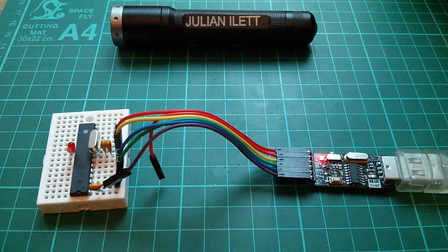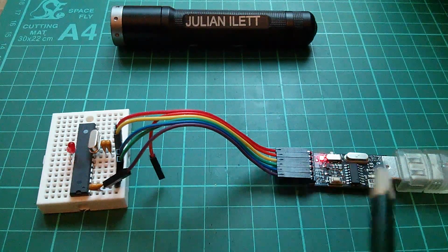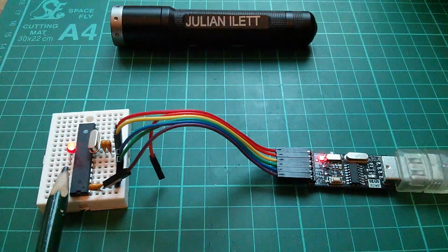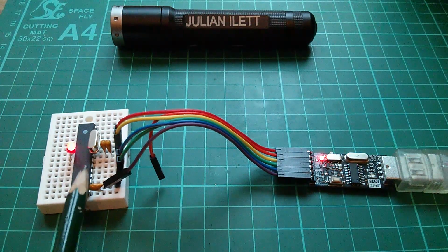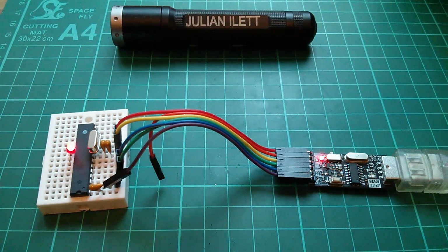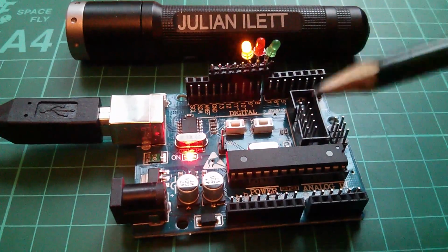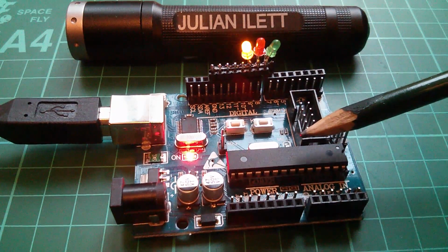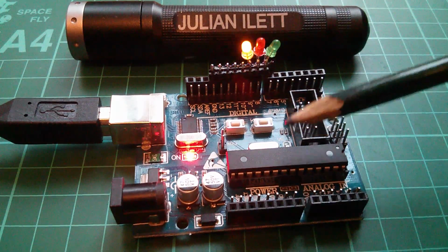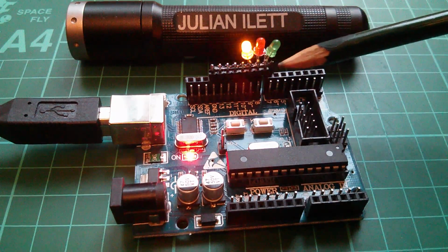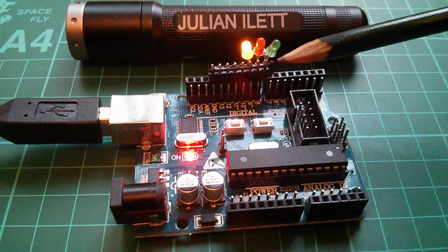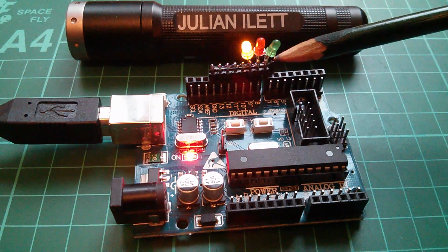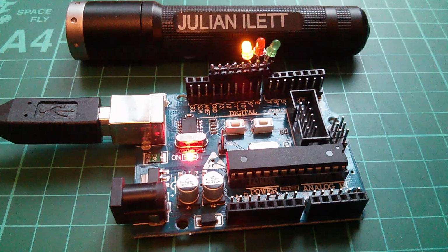And yeah, that seems to have worked. The bootloader has taken, the program has gone in, it's the fast blink that I had earlier. This chip is working as an Uno. So that's it. That's how to use an Arduino as an ISP, an in-system programmer. And I do think that it helps to build this little 3 LED array, because then you get to see the heartbeat, any errors that might occur, and green for successful programming. Cheerio.